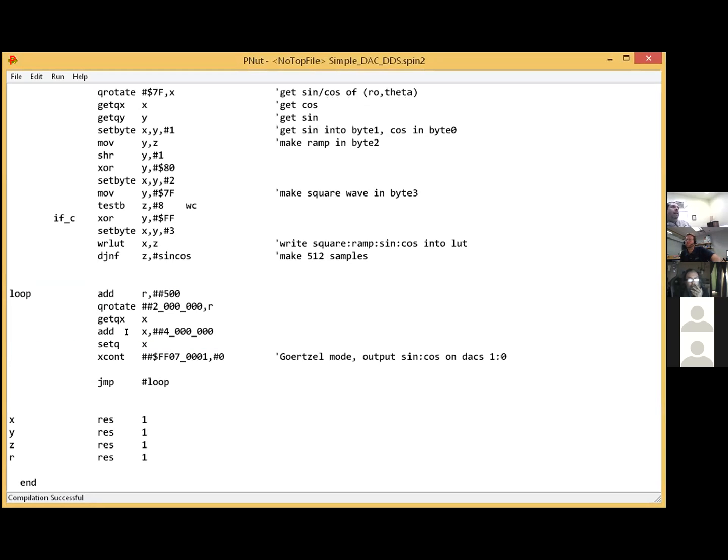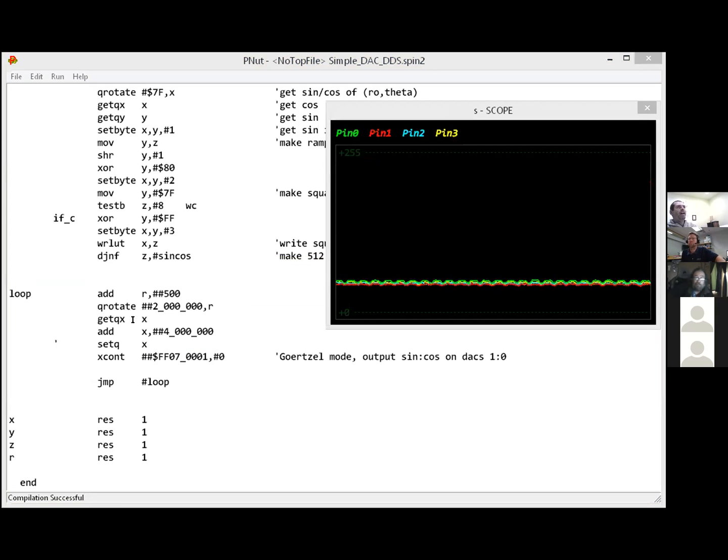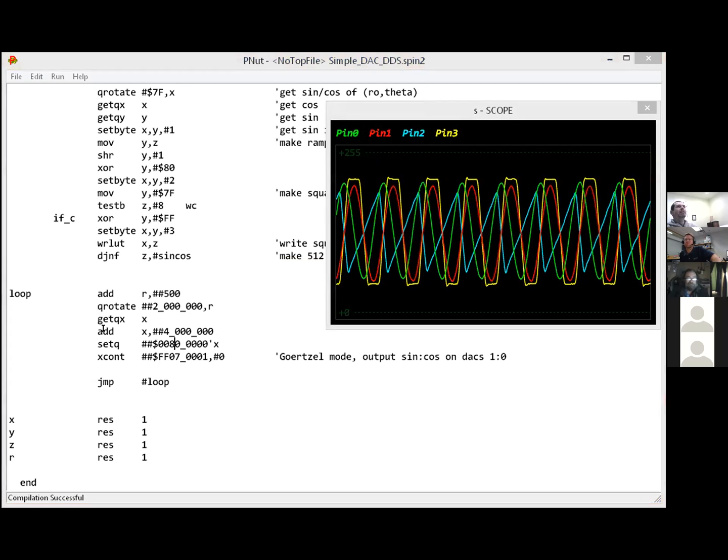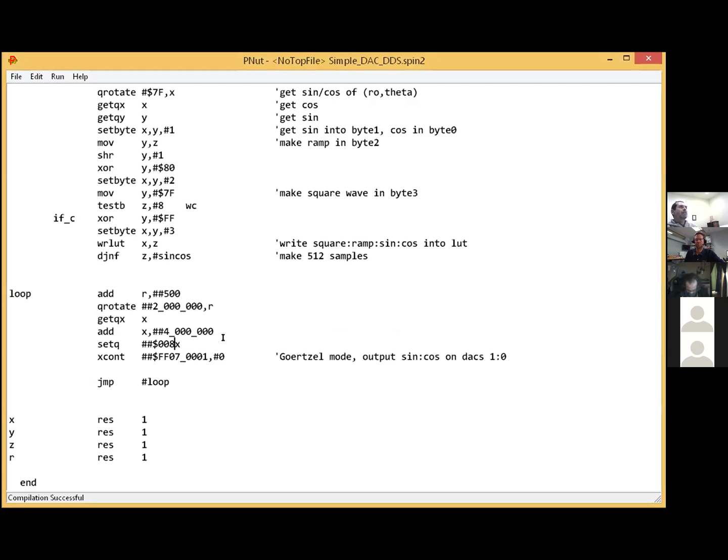So let's say I want to go max speed here. Oh, it's so high that it's being attenuated by the ADC. But let me just put a value in here. It's still too small. Oh, wait, you know why? Because this is 512 steps. To get it to go through every step, we need to use this number here. Okay, now it's 1-to-1. There's no FMing now, but you can see all 4 functions there. Let me put it back the way it was.